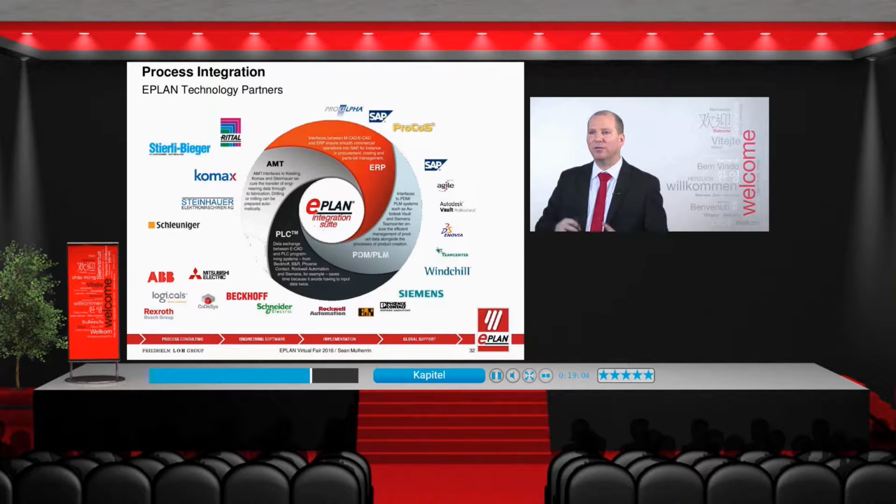Here you get a little bit of an overview of the various different interfaces that we have today as a standard inside of EPLAN. So from an ERP perspective, we can exchange data with SAP. With a PDM PLM system, you can see with Siemens, with Windchill, with Teamcenter, we can exchange data. Or with our PLC systems, we can bidirectionally exchange with various different PLC manufacturers. And finally, automated manufacturing technologies.